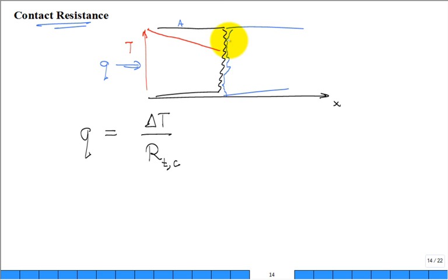And then the temperature gets right here, and there's a jump down in the temperature. And then there's another slope in material B. They're not necessarily the same slope because they have different thermal conductivity. So the dT/dx is different because of thermal conductivity. So you have a change in temperature from node 1 to 2, then a change in temperature from node 2 to 3, and a change in temperature from 3 to 4.